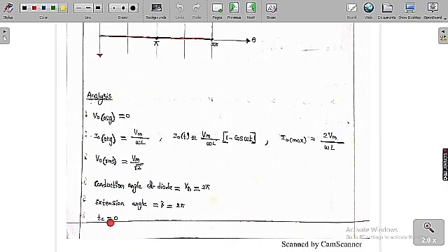And here the diode is always conducting, so there is no reverse voltage. As there is no reverse voltage across the diode, the circuit turn off time is also equal to 0, because circuit turn off time indicates for how long you keep a reverse bias voltage across a diode or any thyristor or any switching device. So it is 0 in this case.